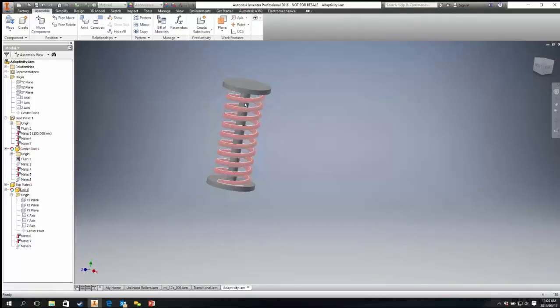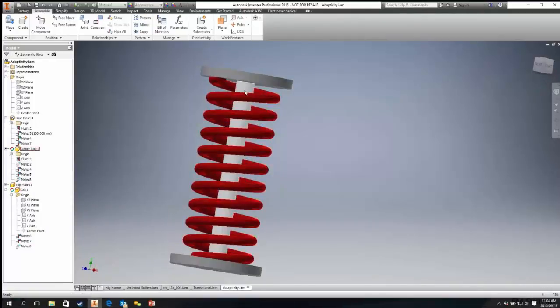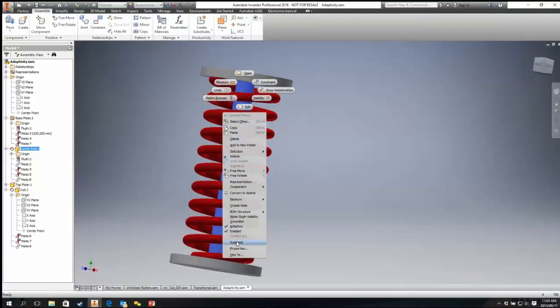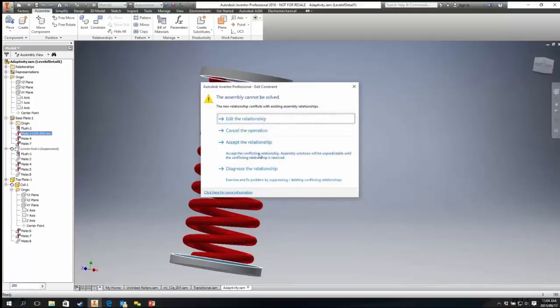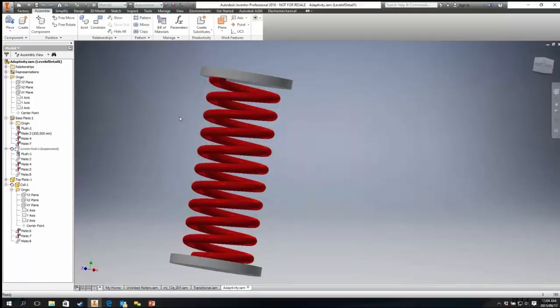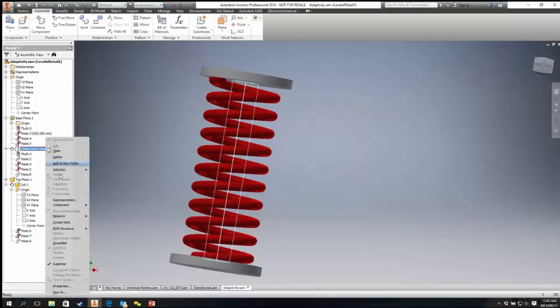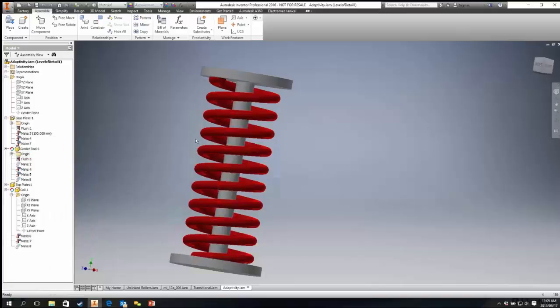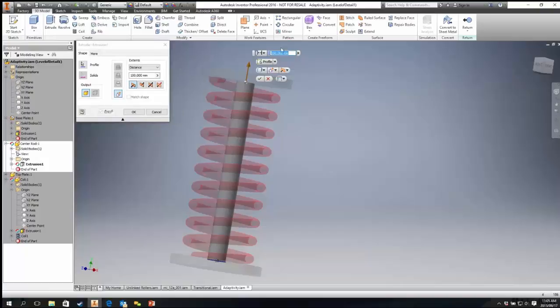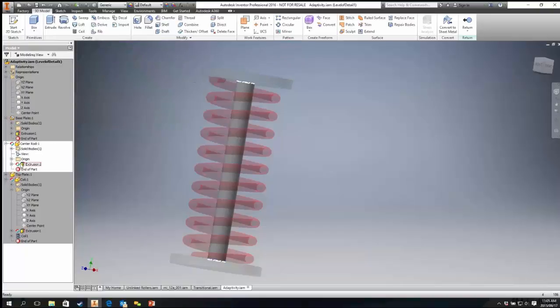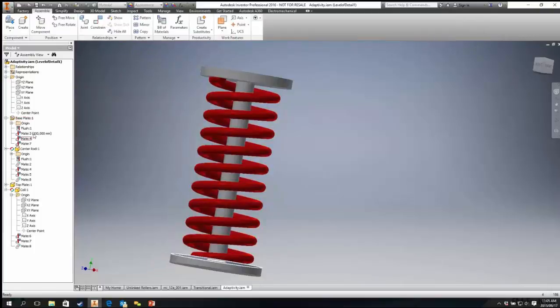Okay, you'll see that I can go and override this value, say 200. Okay, it's still, sorry, it's not suppressed. If it was removed from the assembly, it wouldn't be a problem. So I'm not going to do that yet, because I want this cylinder itself in the center to also be able to change in its height value. So making sure that the cylinder itself, the extrusion, is also set to a value of 100 in this case, but it's also adaptive. Then I can make sure that the part's adaptive. So if I ever override this value, it'll automatically change that height.